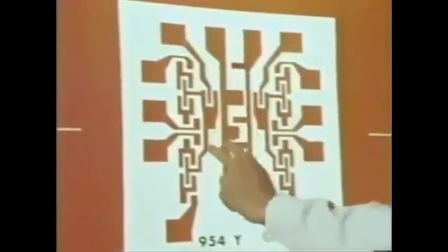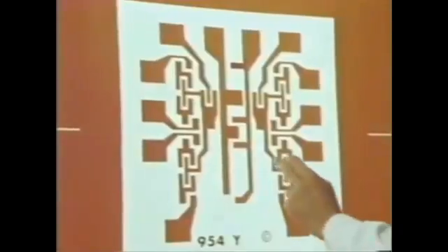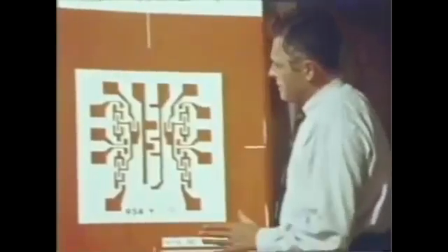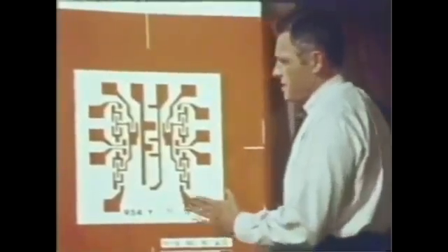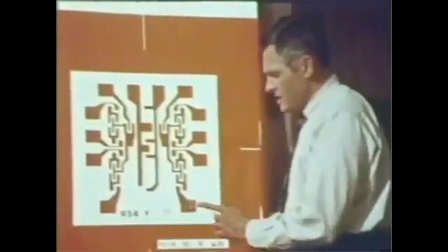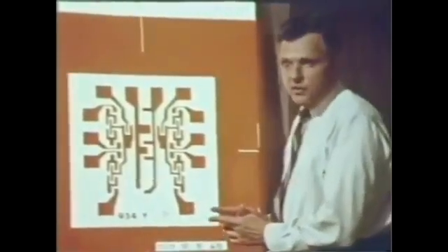Here we have the transistors. And here are diodes and more interconnecting metals. The problem here is to very carefully and precisely convert this large-scale drawing into a small, precise version of this on a 2 by 2 inch glass plate. This artwork is reduced 500 times by a process of high-resolution photography to a glass plate upon which the pattern shown by the artwork is successively stepped and exposed all the way across the glass up to 1,500 times, which means, of course, 1,500 integrated circuits.